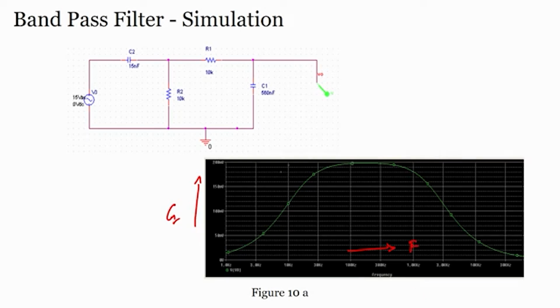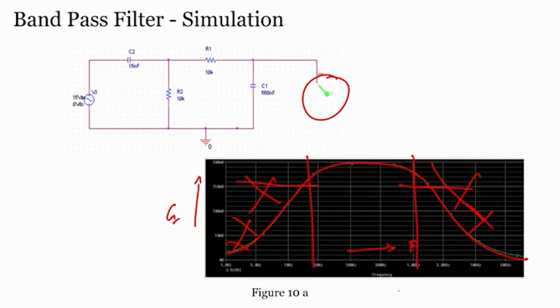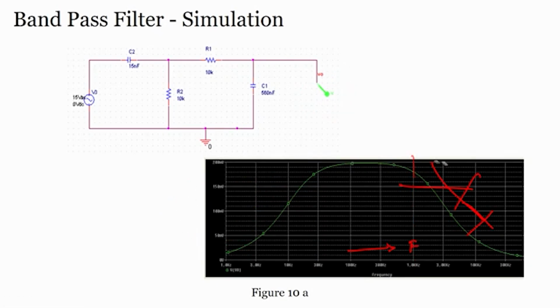And when I design this, I see at the output voltage a plot similar to this, and I have a band which I am allowing to pass. Outside this it cannot pass. There is a band at which minus 3 dB we have to calculate. So, we can have some band which is around this value, right. This you can do again with simulation, and you can find whether it makes sense or not, right. The point is you can design a band pass filter with your passive components,